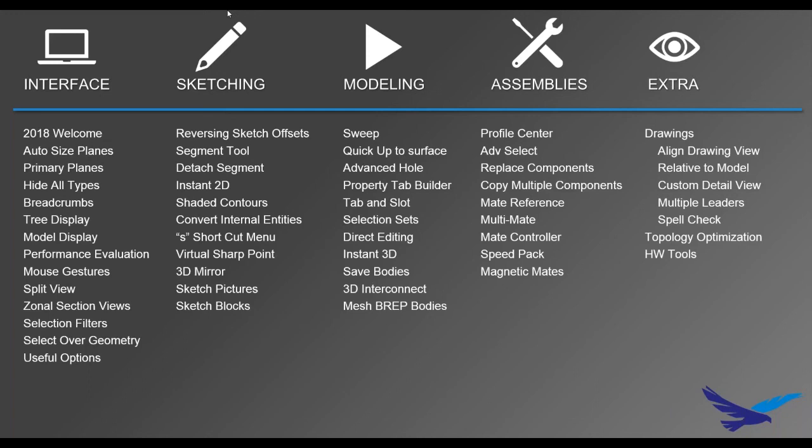Okay, how do I repair out of context or broken references? Okay, out of context references, if you right click on the part that is out of context, there will be an option there to edit in context, and then it'll open up wherever the reference was created. You can also list all of the external references, and you can delete them to remove the references like that. Broken references, you can only delete. Once you break a reference, you can't unbreak it. That's why freezing them is better. But there's a whole course on that in the assembly modeling class. So I really recommend, if you're confused about the references and things like that, jump into that class. That will definitely help. All right, I think that was all the questions.